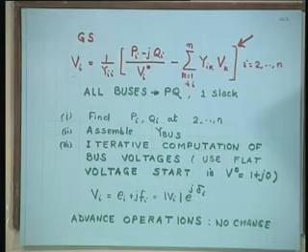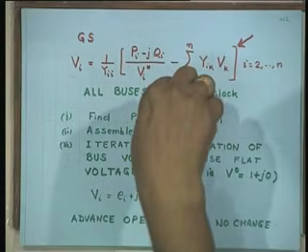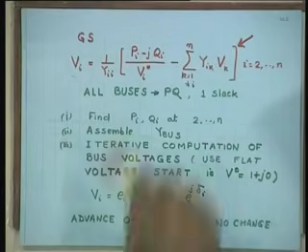If you remember, I told you that 85% buses are PQ, 15% buses are PV, because there are not many generators. Where is the money and where is the need? So, one is slack, roughly 15% are PV, and the remaining are PQ. So, this assumption is closer to reality.